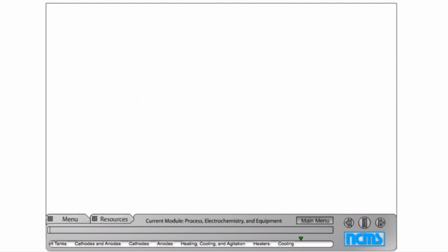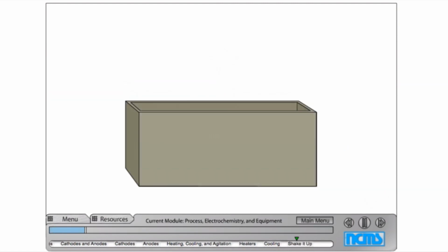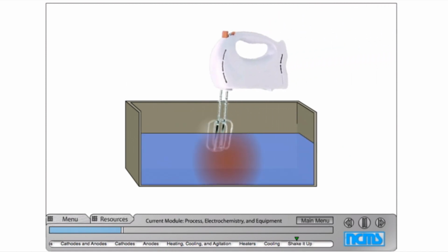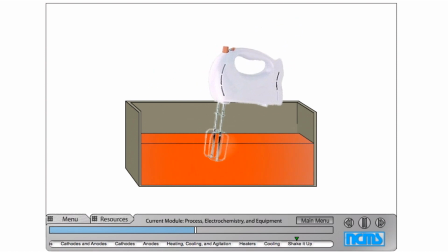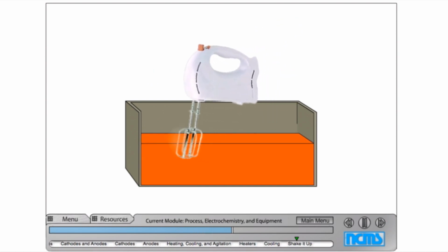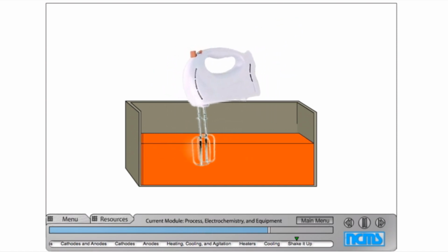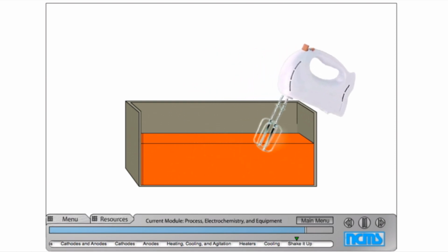or damage. Finally, plating shops agitate their baths to keep the chromic acid moving throughout the plating process. Not only does agitation help even out the temperature, it can improve plating quality by dislodging hydrogen bubbles that tend to form around parts being plated.